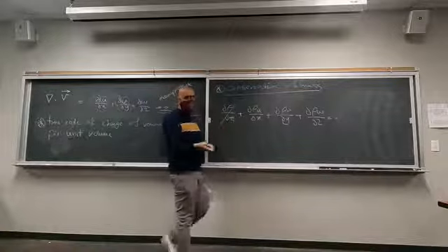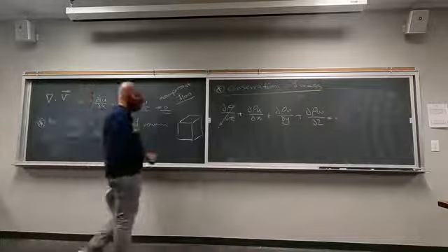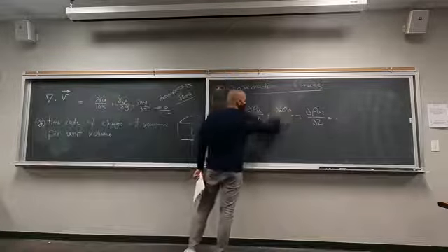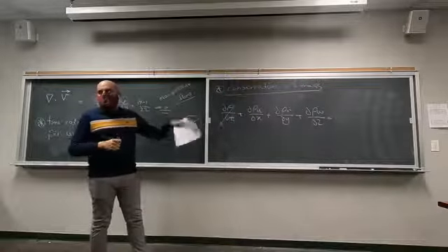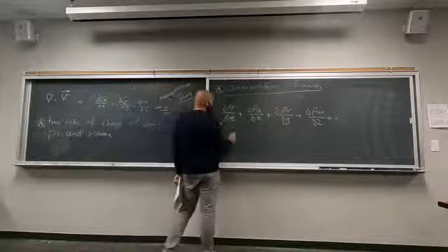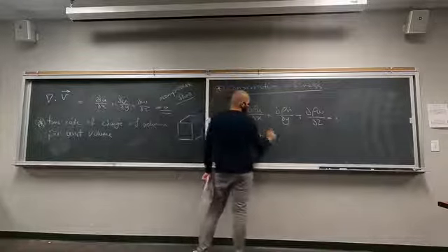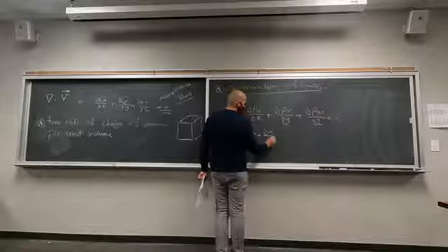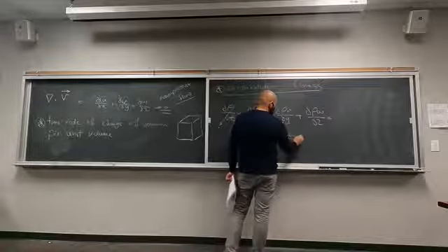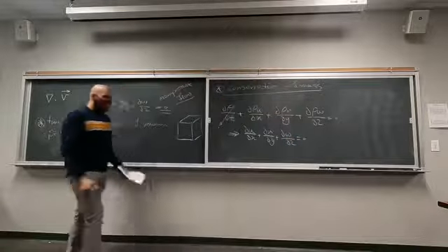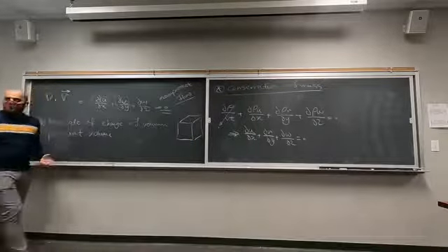It doesn't really matter if you are in the steady state condition or transient. Changes of density is going to 0, and we can take the density out of these partial derivatives, right? And we have 0 on the other side, so we can essentially cancel density. So for an incompressible flow, you're going to end up with this equation, which is the divergence of velocity.